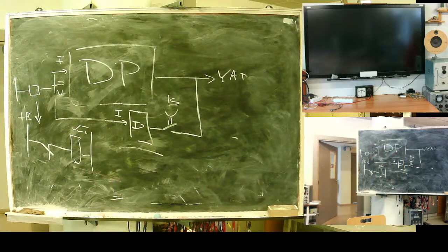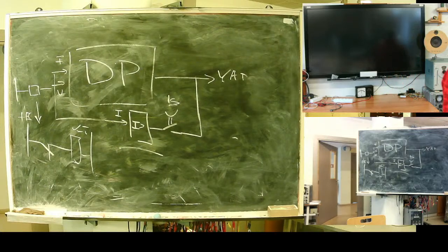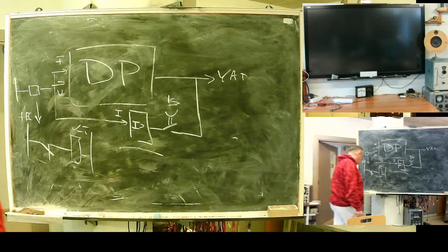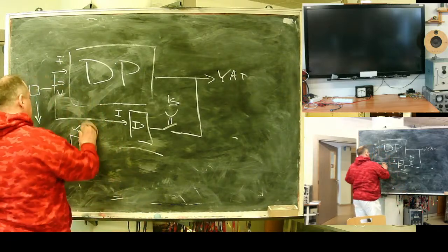To decrease damage of fault, if you have distance protection on both sides of a line, and there is a communication infrastructure, use trip signal propagation.